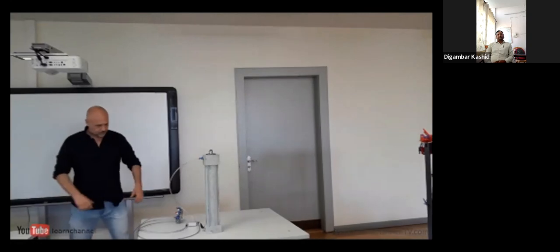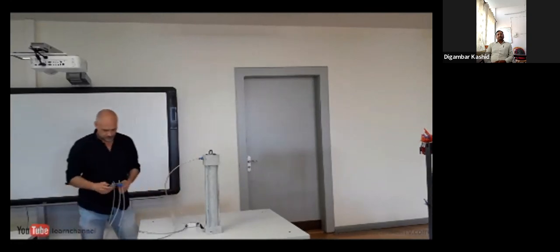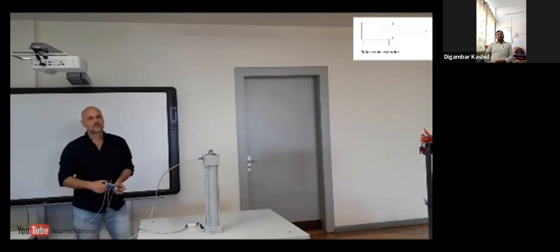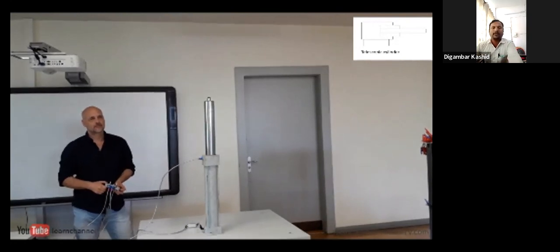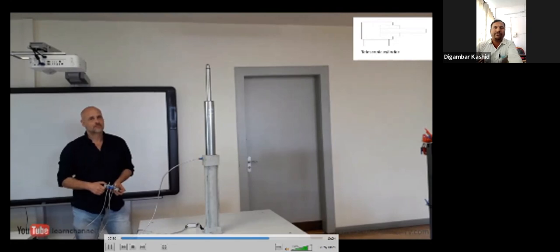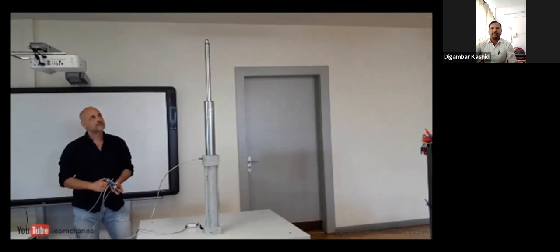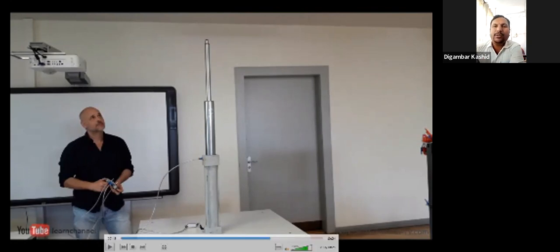You need extra distance? Then take a telescoping cylinder. Also called a multi-stage cylinder, this type of cylinder consists of a series of tubular rods called sleeves. These sleeves sequentially decrease in diameter and are nested inside of each. Please see how that lifting of one cylinder after another cylinder is happening.